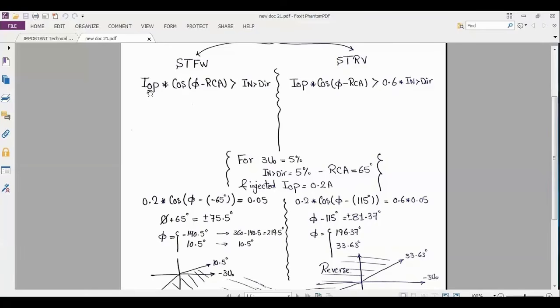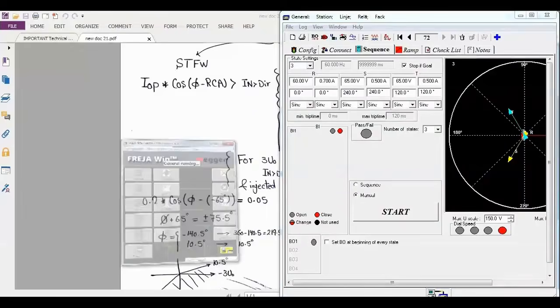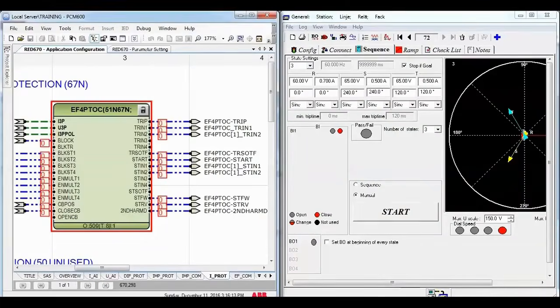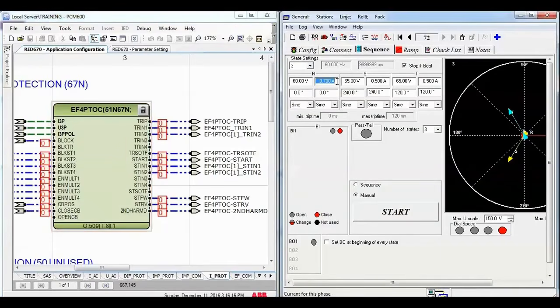That's why I said it was found at point 2. All these calculations were done based on a 9-volt reading at point 2. If you change the point 2, everything will still be calculated according to these coordinates in the forward and in the reverse. So I must adhere to what I had calculated based on. I calculated that the operating current would be 0.2, so I set it here to 0.7.